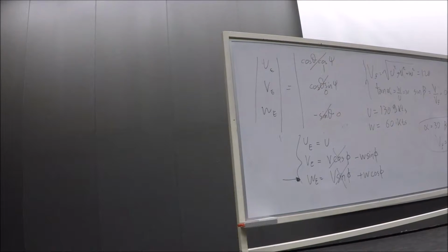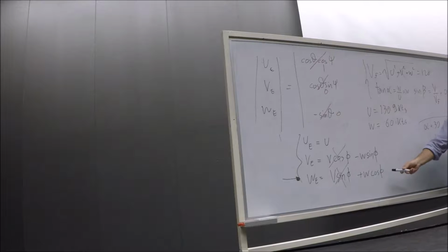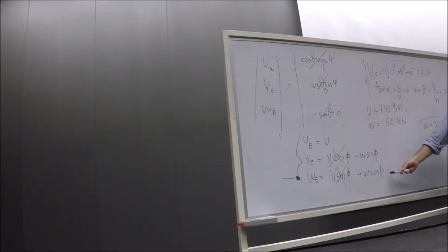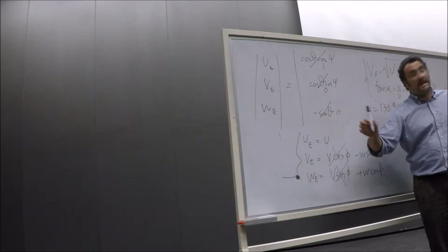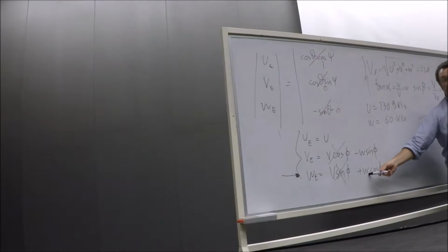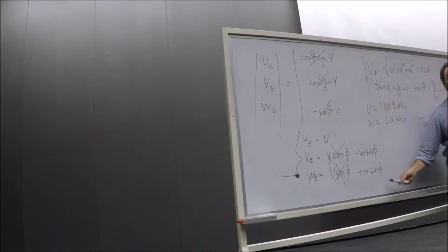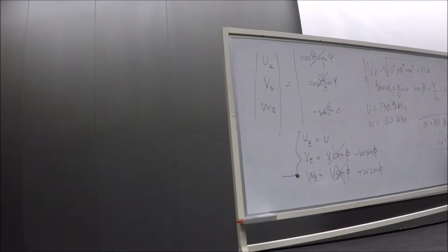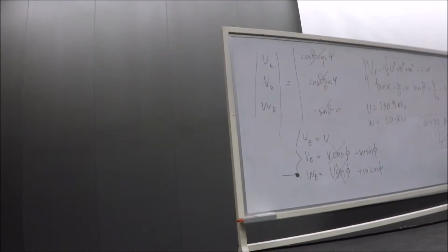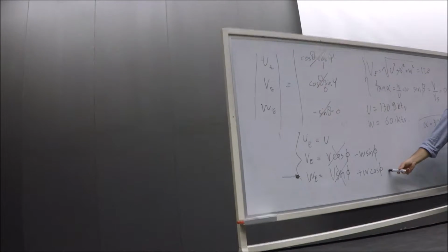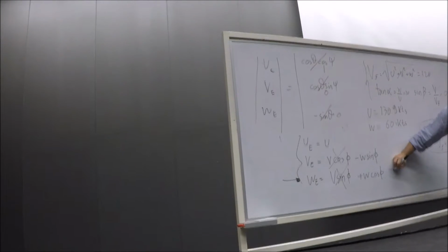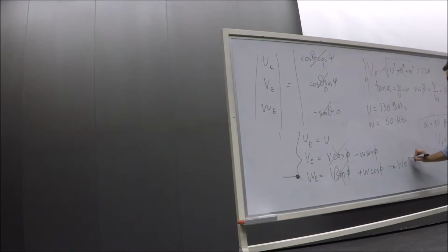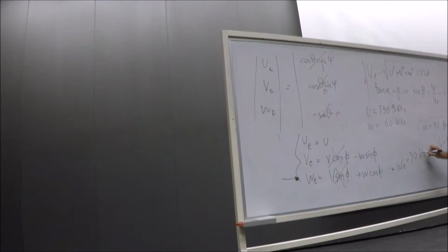Okay, so with this value of W, we can go into this equation to find WE, the vertical velocity in the z direction, which is equal to W multiplied by the cosine of 60. It was 60, yes, which is 1/2. So WE is equal to 30 knots.